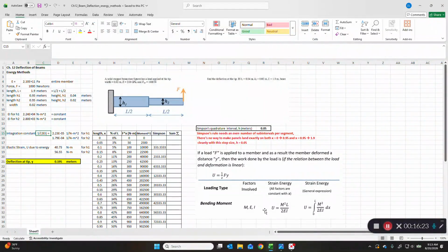And so we want to know right away, what's our integration constant? You can see here in the integration, 2EI are constants, so we're going to pull that out of the integration. What's 1 over 2EI? Well, EI you have to calculate, right? So E, and then you have to figure out I based on 1/12 of the base times the height cubed. So there are your EIs. You've seen these before. So these are constants, so I'm pulling these out, right? EI for H1 and EI for H2. And the units are newton meter squared, okay, for those EIs.